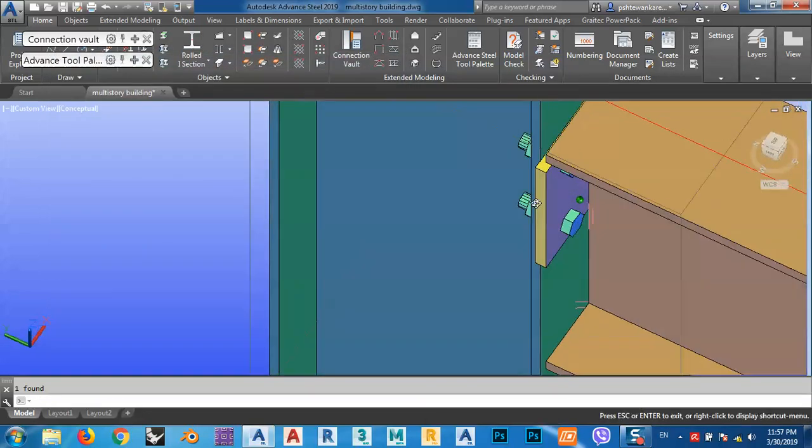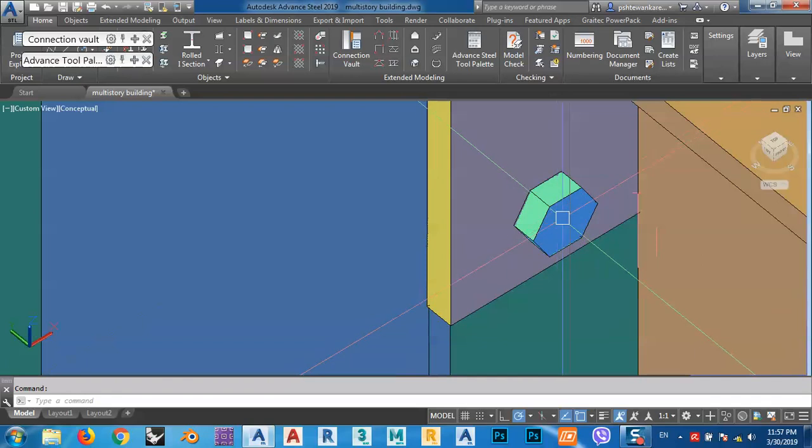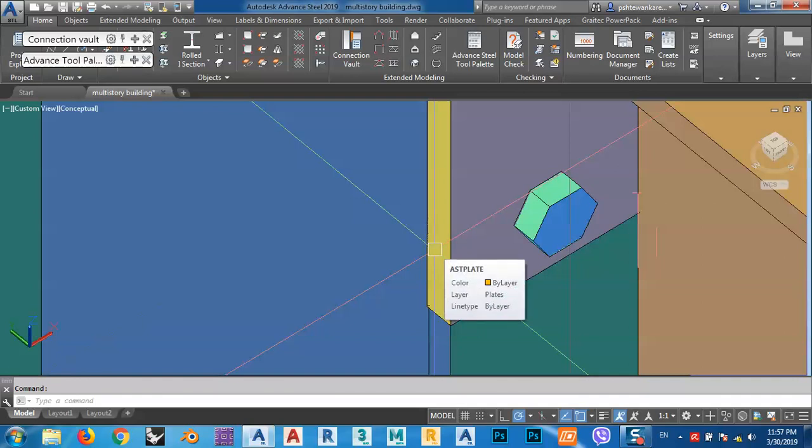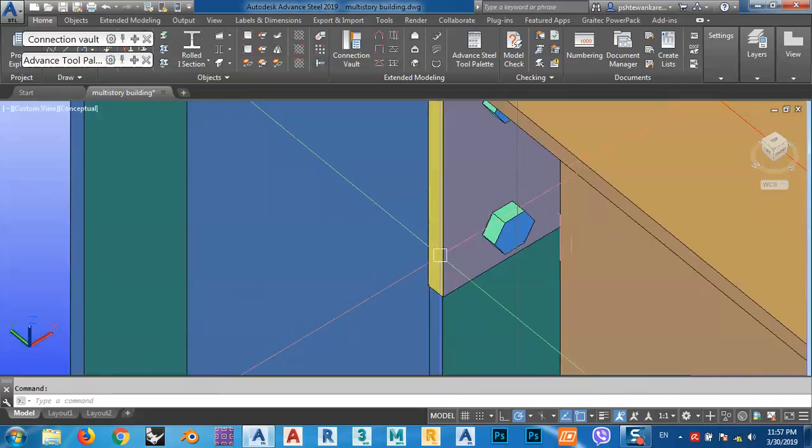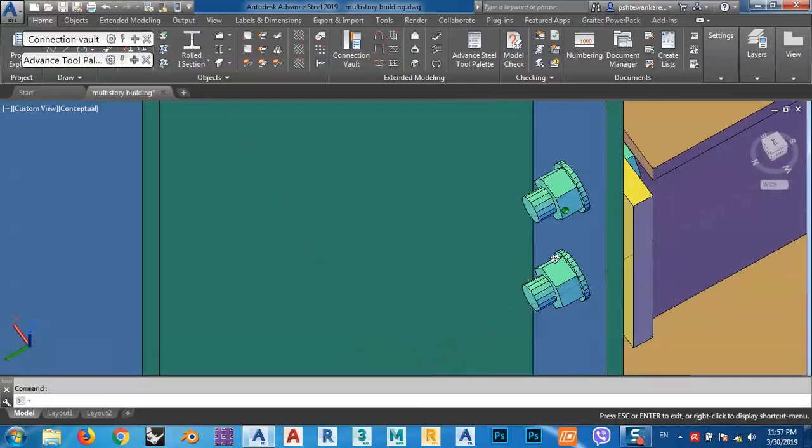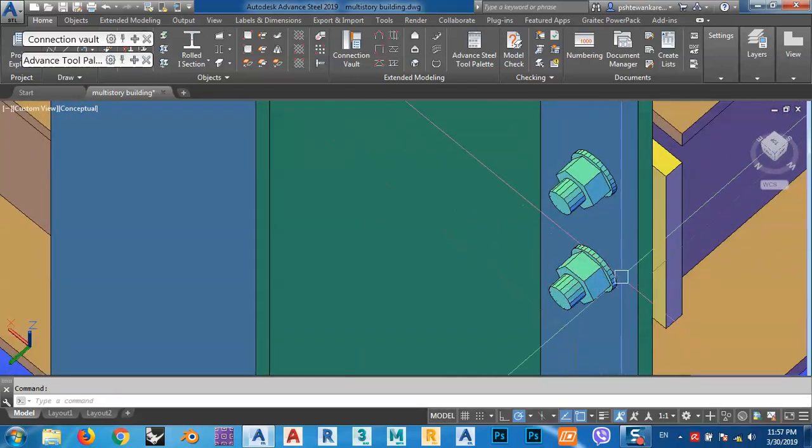If I take the edge distance between the center of the bolts and the edge, as we know, it should not be less than 1.5 times the diameter of the bolt. This is a rule we have. I cannot take it from the edge of the plate, because if I took this 1.5 bolt diameter from this edge, it would be less for this column. So I have to take 1.5 diameter of the bolt from the edge of the column.